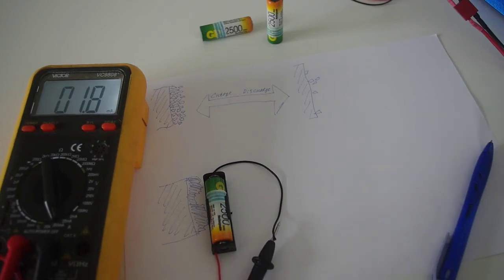After that, just put this one, the discharged cell, in the charger and make sure that the charging current is as low as possible. So do not use quick chargers, use slow ones, and use intelligent ones that will stop the charging after the cell is fully charged. And just repeat this procedure with all cells that you have. I have 4 of them, and let's see what happens.